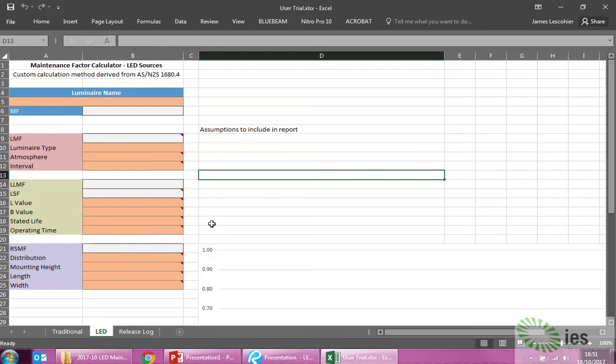So, have you got any comments on TM21 for LED? I don't specifically have any comments on it. Well, colour doesn't play into this too much, and the data from those standards or methods are approximates in that you run it for a number of hours and then you multiply it by the number, 6 or 10 or whatever it was, and that sort of gives you your answer as far as an estimate of life.